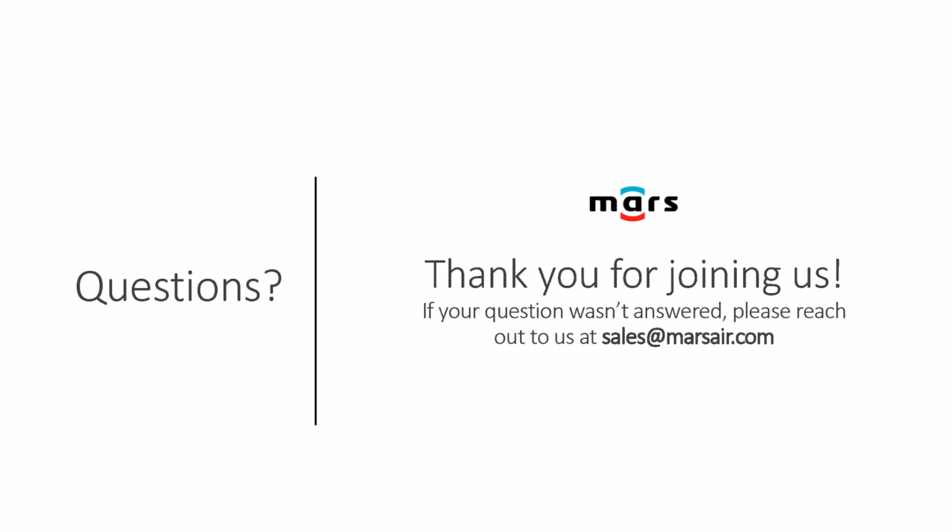Thank you, Naga. I think I have just one more question here. It says, if the air curtains are installed outdoors, do they come with any protection against weather or other environmental factors? All our unheated air curtains are rated for indoor and outdoor installation, but there is a caveat: if it is going to be installed outdoors, it's only rated for mild weather. It's a very loose and generic term, but what mild weather really means is slight mist, indirect rain, and of course it can be exposed to snow or ice.